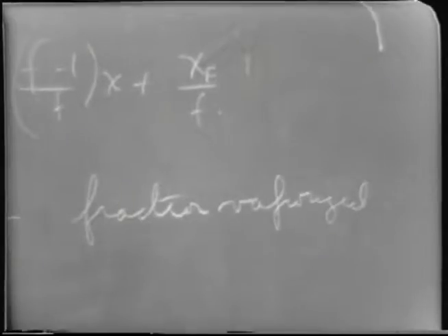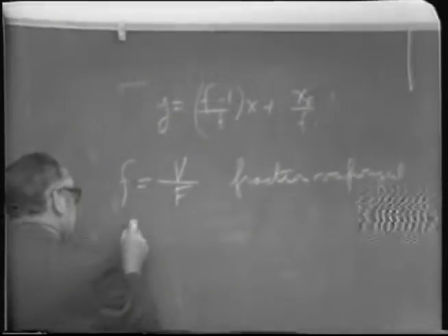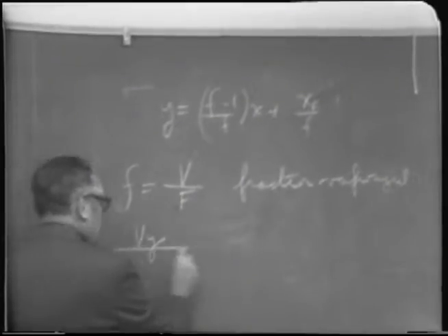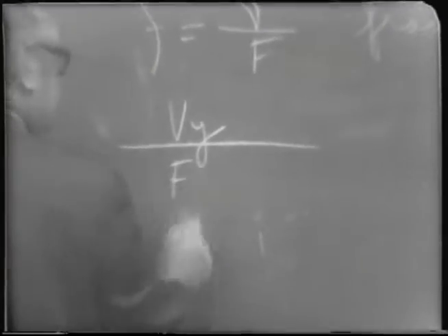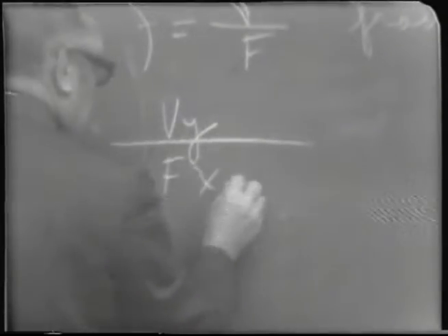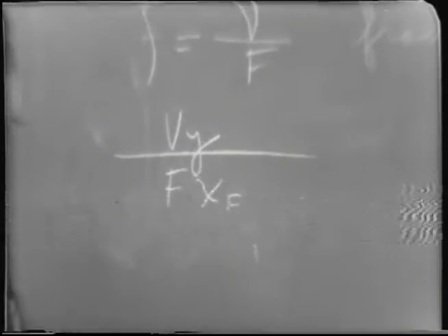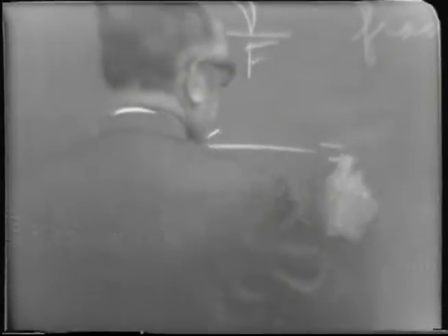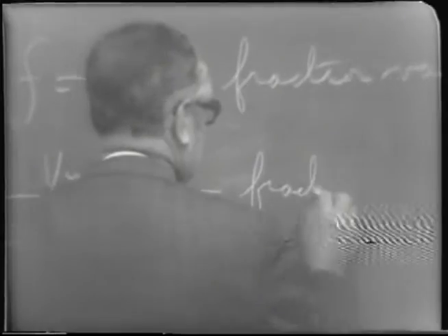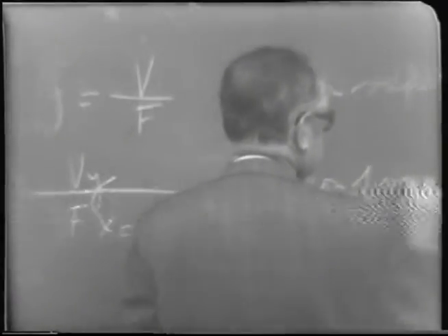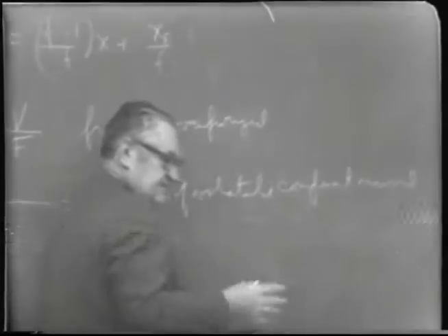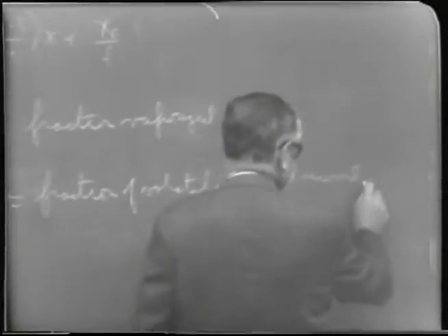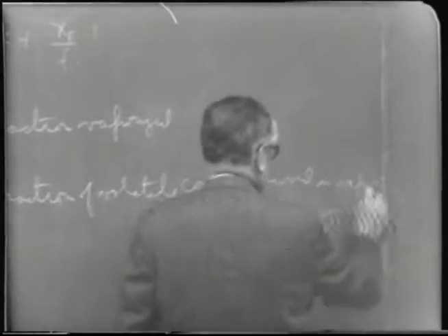You might note also that if you multiply the amount of the vapor by the concentration of volatile component in the vapor and divide by the feed, multiplied by its concentration of a particular volatile component, this is simply the fraction of the volatile component recovered in the vapor, in the vapor stream.